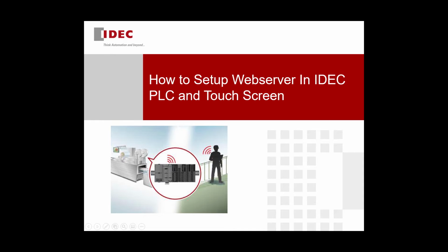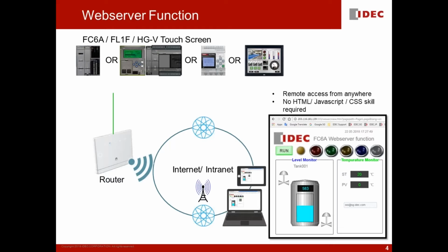So this hour, I will mainly talk about how to set up web server in our IDEC PLC and touchscreen. If you attended the previous webinar session, I believe you have seen the web server function introduced by me. Let me give you some refresh again. This function is supported in IDEC FC6A Plus PLC or FC6A all-in-one PLC when used together with HMI module FL1F and any model of our touchscreen. You might have a question, what is web server function?